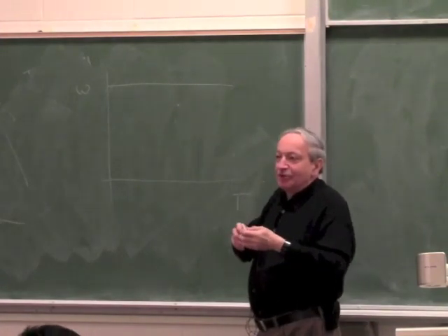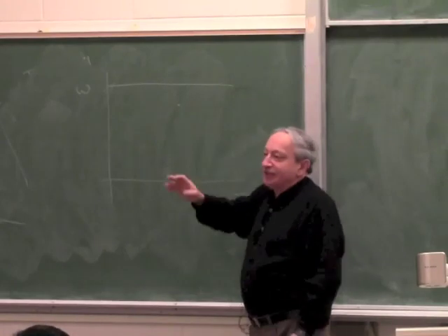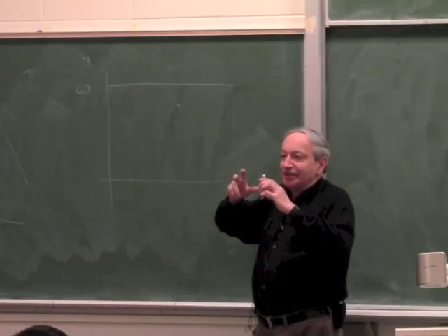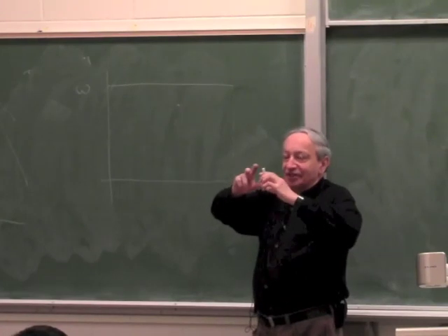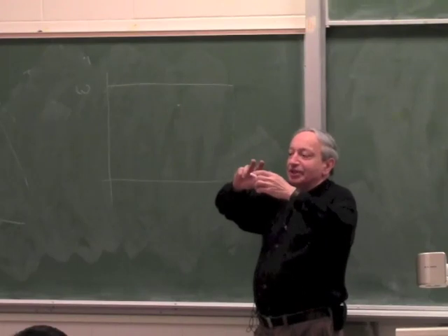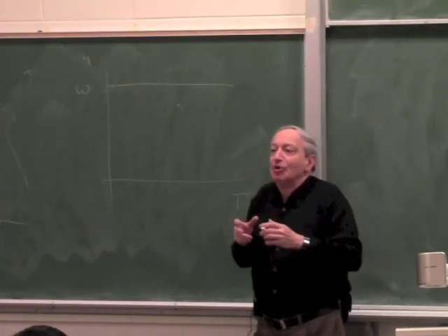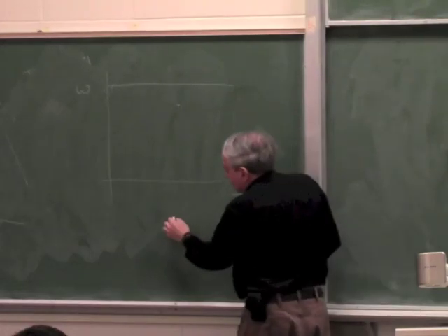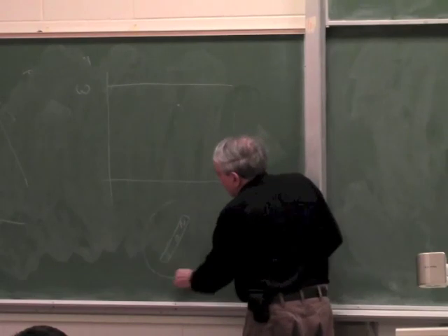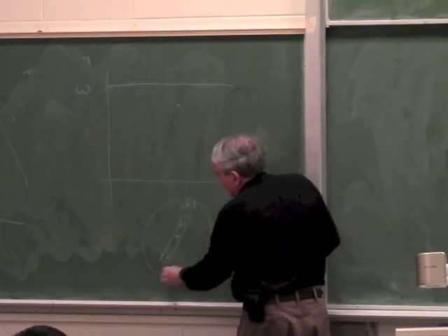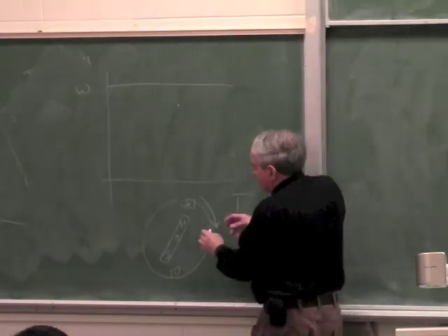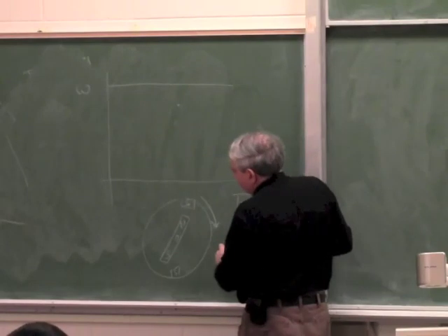It can't follow anymore, because remember, the rotating field creates the equivalent of a rotating magnet. The armature is another magnet, and the one magnet follows the other. But at some point, there is so much torque that the magnet can't follow, because the torque is more than the torque the two magnets can generate. Remember the analogy: you have a rotating magnet NS, and the rotating field looks like a ring with another two magnets on it, and this ring rotates and this is following, but as it follows, it starts winding up.